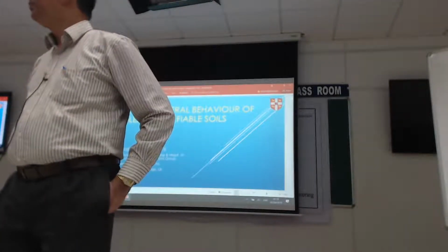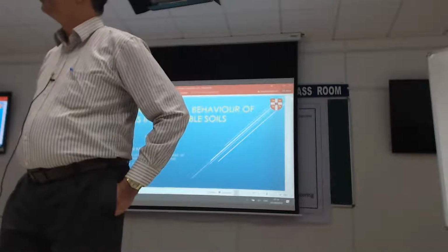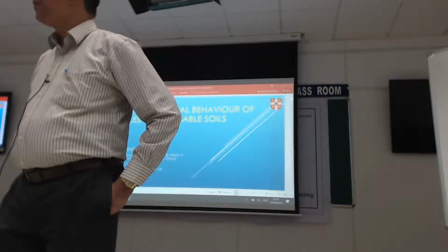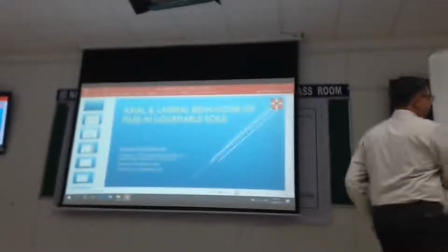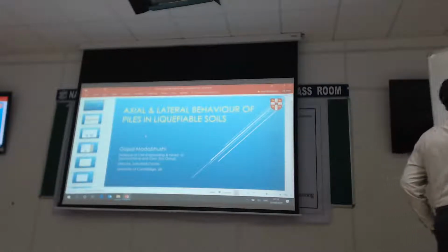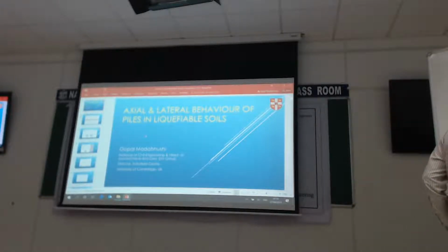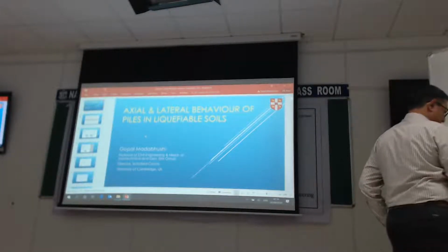Yeah. So what if there is any non-liquefiable layer sandwiched between two liquefiable layers? In that case, how will the pile behavior change? So where are you talking about the non-liquefiable layer? At the top? No, in the middle, as a sandwich between two liquefiable layers.